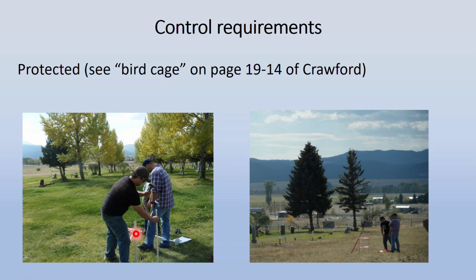Plus, these lath actually serve as your tablet out in the field. You can write the name of the control point, possibly the elevation if you want to report that, and they just convey information to both you in the future and other users who weren't there the day that that control was established.